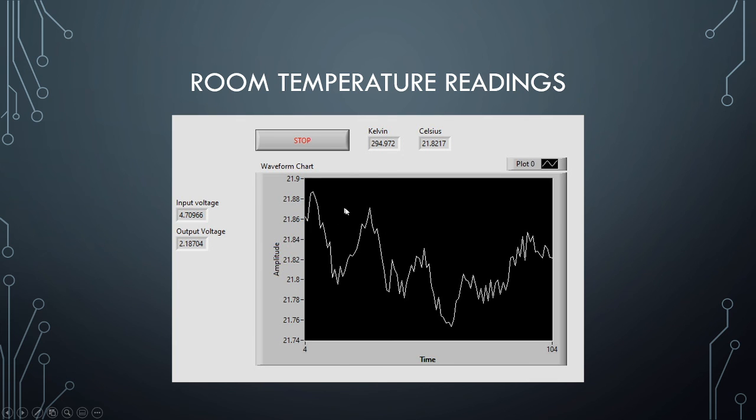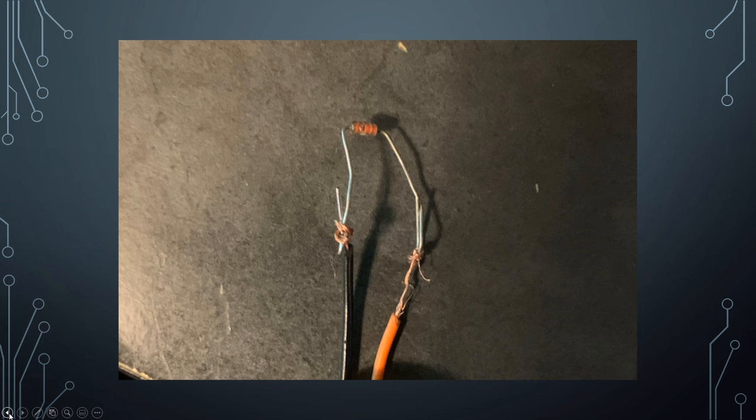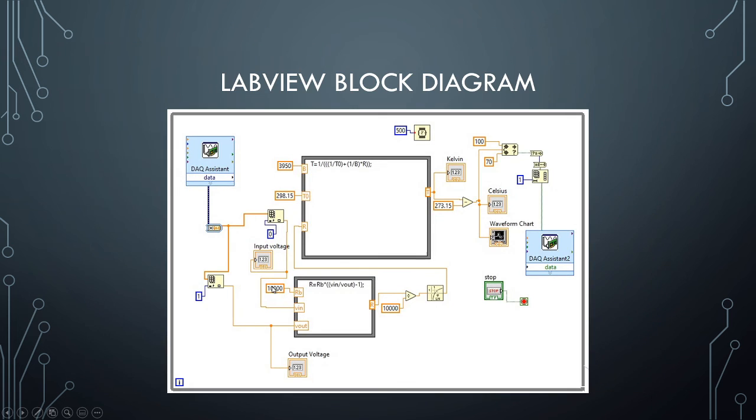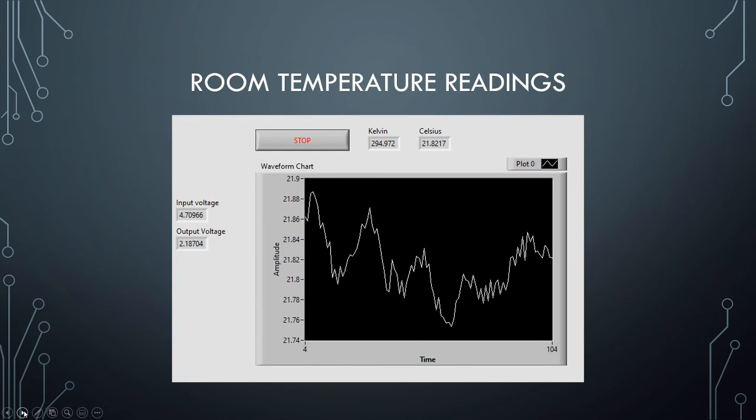But yeah, other than that, I think unless some of the nominal values here, because it's 10,000 ohms plus or minus 5%, and then if that was on one side and our thermistor was on the other side of its tolerance, then we could see a couple degrees difference probably.